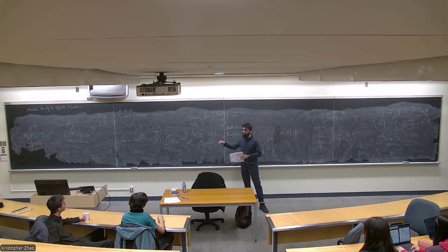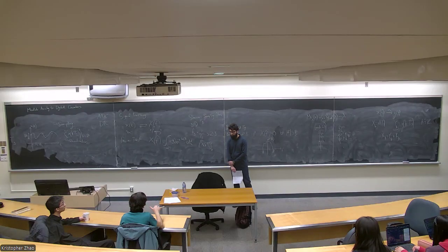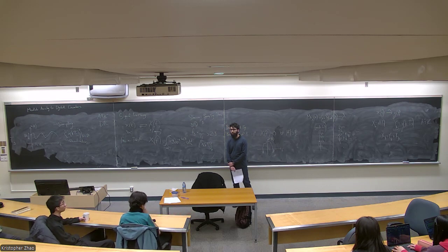Formally this theorem requires all points from negative infinity to infinity. However, even a finite number of them is able to produce a very good approximation to the whole signal. So formally it requires all time, but even with a finite amount of time, it's still a very good approximation, and the recovery is of very good quality. But it's not that a finite number will exactly reconstruct the whole thing; it's only an approximation.